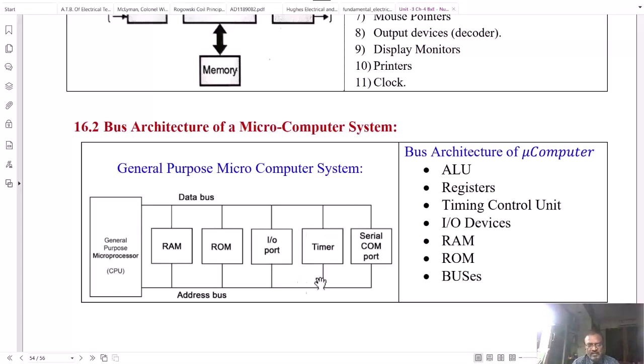And these are the hardware available. Timers can be small 16-bit timers or 32-bit timers, or it can be a real-time clock itself, so that you can set any time of a day and you can trigger the event when that time reaches. Such things can be done by the timer hardware, which is programmable under the user program, which is executed by the microprocessor system or central processing system.